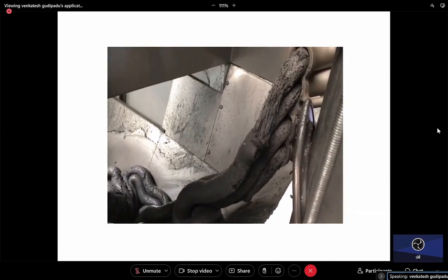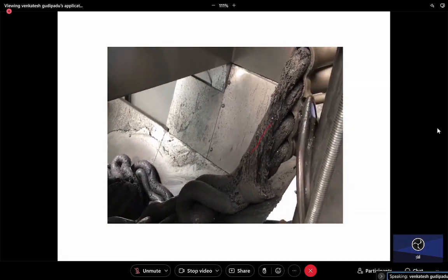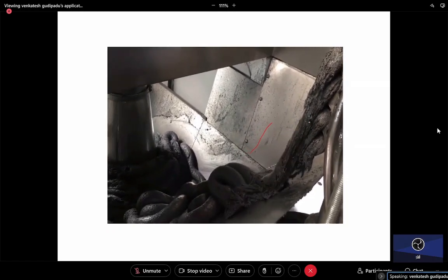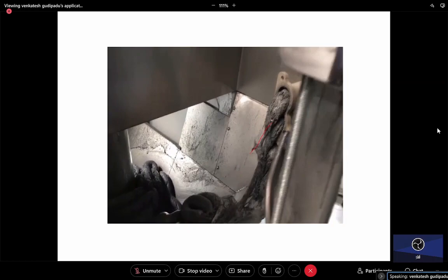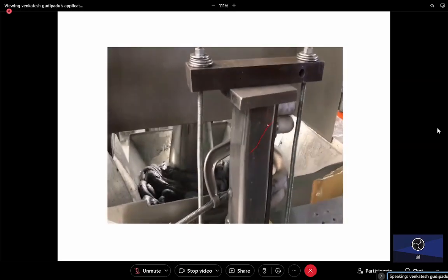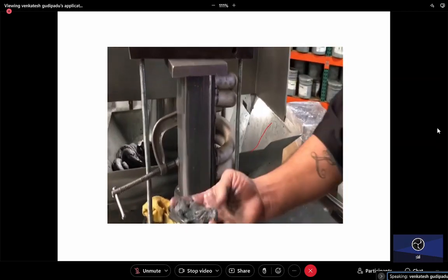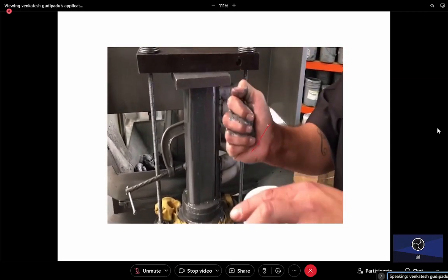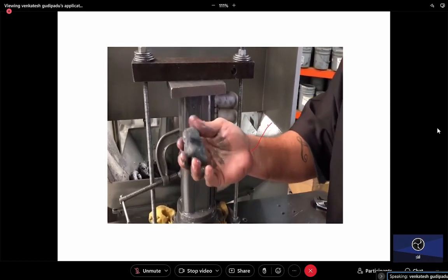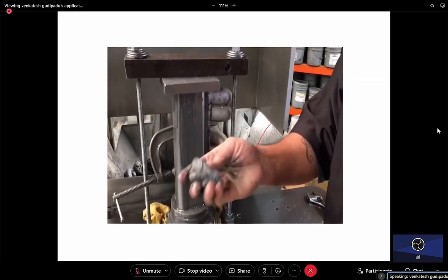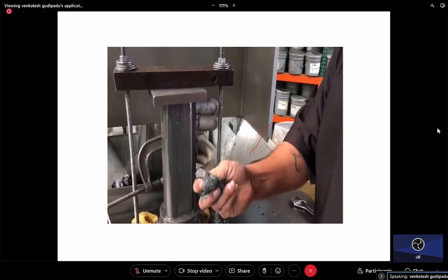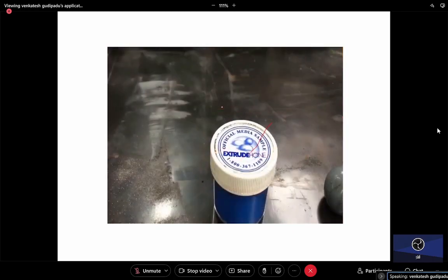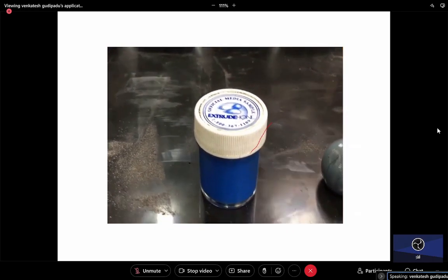So this is the semi-solid media I'm talking about in my case study, in my work. This is the mixture of the polymer gel mixed with the abrasive particles. And what is my job? What is the experiment we are doing here? We are finishing the manifolds. Manifolds are used in automobile car engines, and the finishing of the internal geometry of these manifolds is important.